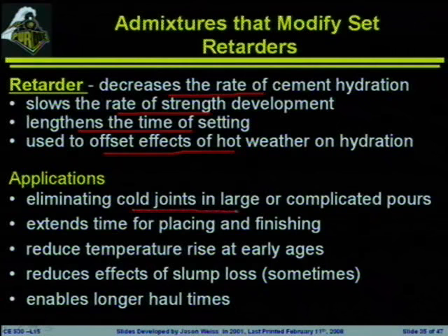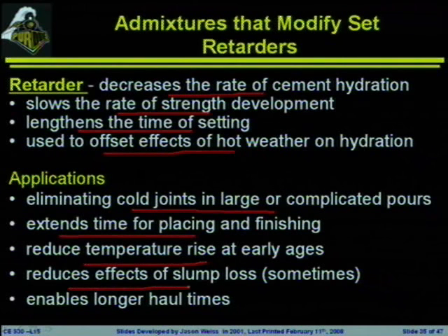In large pours, you may see a retarder being used, especially if it's large or complicated. I will show you an application of this in bridge decks that I think is a novel and interesting application. It can extend the time for placing and finishing the concrete, can reduce the temperature rise at very early ages, and can reduce the effects of slump loss.